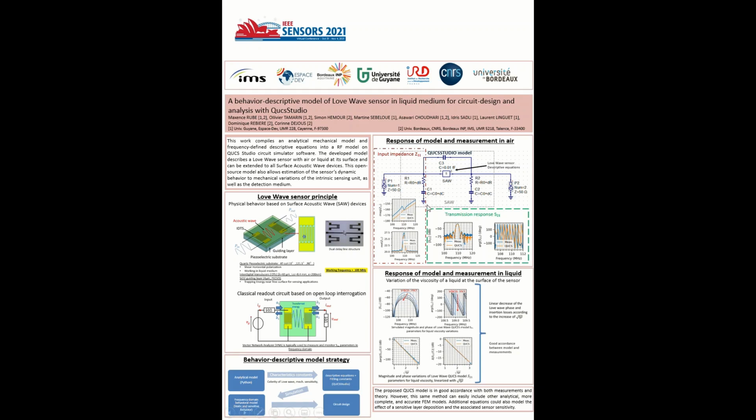A simple example is presented here for the response of the model in some measurement in the air. The block here contains the descriptive equation, and a resistance and a capacitance simulate the purely electrical part of the input impedance of the sensor, right here. Here, the simulated circuit is similar to a VNA characterization. You can observe that the input impedance and the transmission parameters are in good accordance with real measurement.